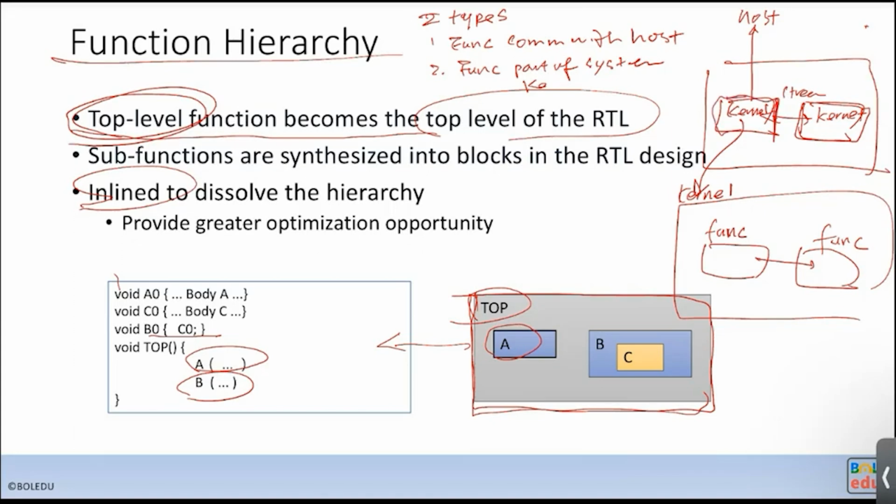If there's a kernel function, that means when you do the HLS synthesis, you specify this part as a top function. You have arguments, and for the arguments you specify the interface type. For the one that communicates with the host, you use some interface arguments such as AXI-Lite. For this kernel function, you don't have anything communicating with the host, so you don't have AXI-Lite.